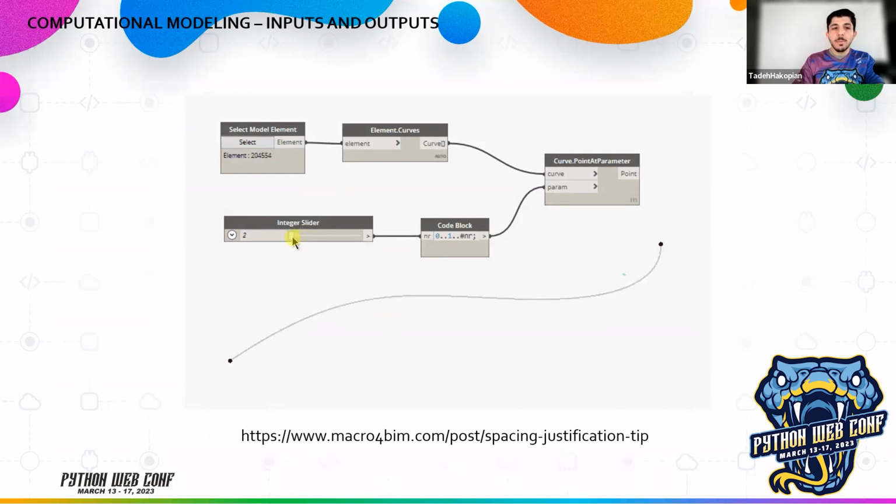Lots of curvy buildings these days. And somebody can then use these tools. And again, these are only 5 nodes doing very basic operations. The selection you see here of the curve is actually generated from the 3D modeling environment. And all we're doing here with the slider is putting more points along the way. Those points could be different elements on a building, could be trees on a walking path, could be a lot of things. And the process is pretty easy to follow, I believe, because people can see, okay, the slider does something. It's adding more things to it. The selection's coming from a model. They can make that model themselves. And they can see along the way, they can change the values so they can do whatever they want.